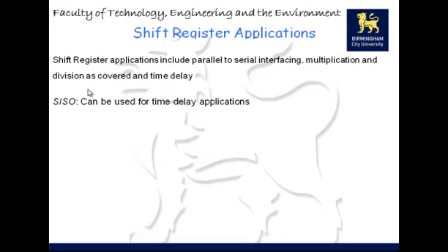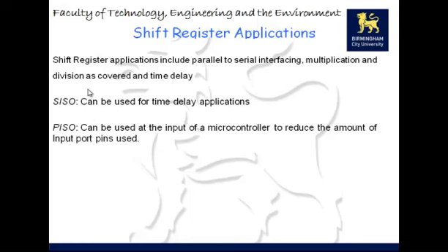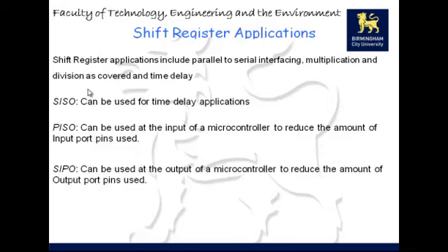So, just to recap, serial in, serial out can be used for time delay applications. PISO, parallel in, serial out, can be used at the input of a microcontroller to reduce the amount of input pins required. SIPO, serial in, parallel out, can be used at the output of a microcontroller to reduce the amount